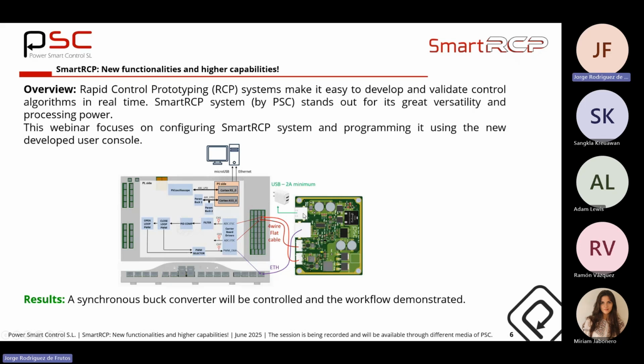In here, we have the input power, so 5 volts input, a couple of wires. Those wires are for the feedback signal of voltage, which is the one that we will use to close the loop, and another one in order to check the inductor current. This Ethernet, the purple line, is intended to carry the PWM pulses for the converter.